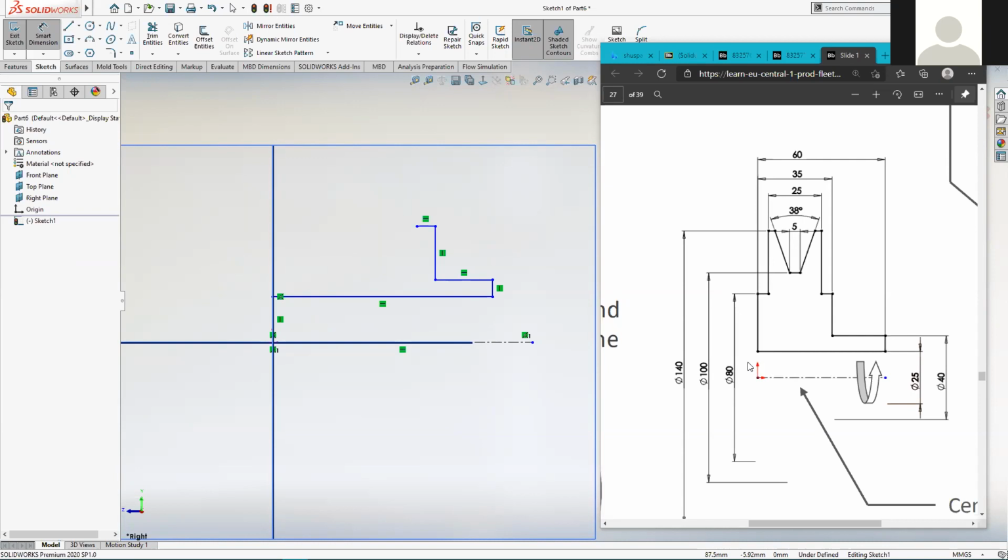And when I say parts such as this, I mean fully rotational parts, parts which rotate through 360 degrees and come back to meet themselves. So undoubtedly the manufacturing process that makes these sorts of parts is something like a lathe, let's say. You tend to refer to the engineering drawings talking about diameter. You tend not to refer to them talking about radiuses. So it's good that we create our sketch using diameters.